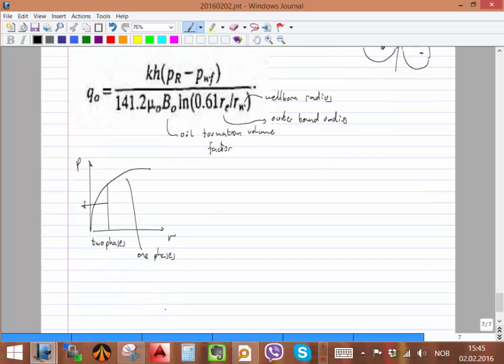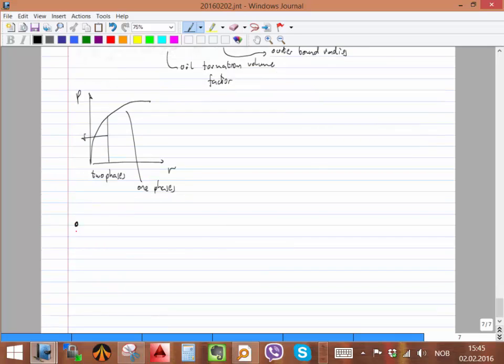But after that, what is another method that you could use for getting IPR? If you have the actual well, you can test it, right? So you do a well test. Let's think about how we do that. Let's say we have a well with perforations, and a formation. Usually some wells already have a pressure gauge installed at the bottom hole, or you lower one with a wire, the pressure transducer, and then they begin to test at different rates. Why not one rate only?